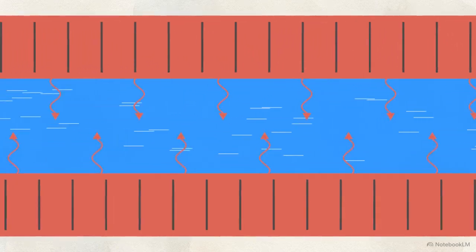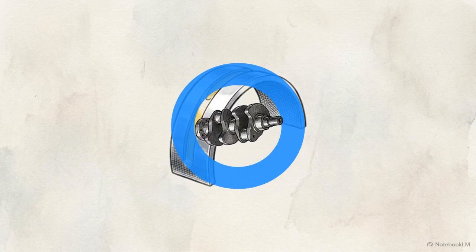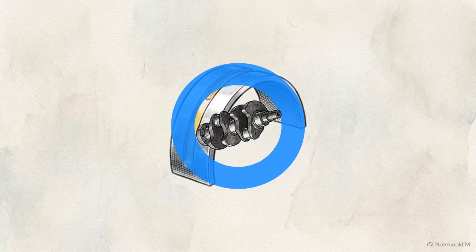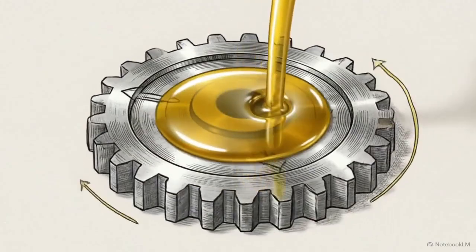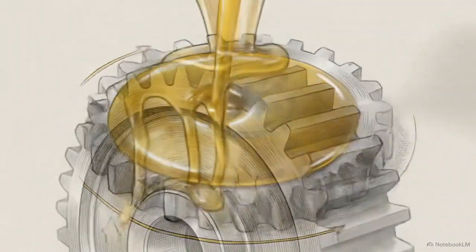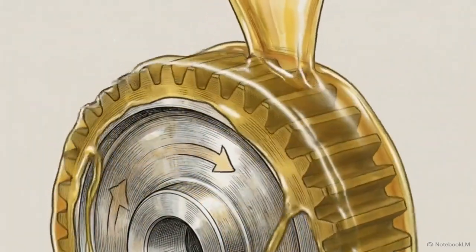We classify this separation by its thickness. High-pressure rotating assemblies require full film lubrication, where pressurized oil keeps the surfaces completely apart. External components, like steering and suspension joints, use boundary lubrication, relying on a semi-solid grease that does not fully separate the parts. To survive kinetic and thermal loads, an engine cannot rely on grease. It requires a highly engineered, continuously flowing liquid boundary.